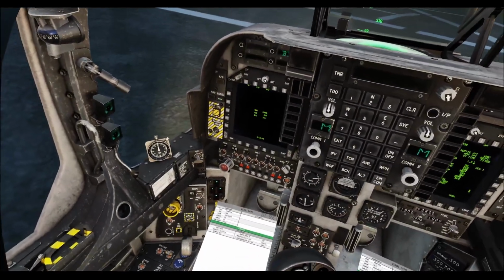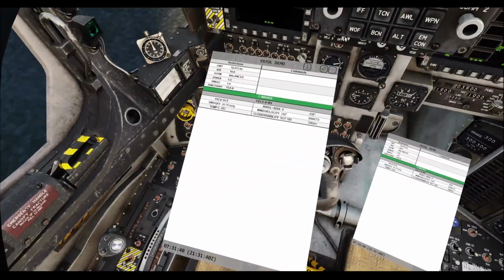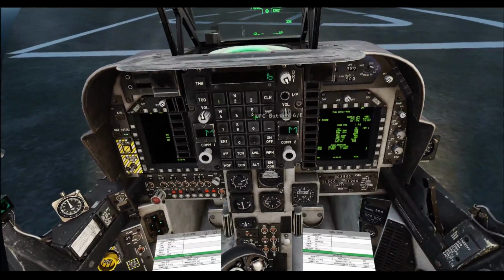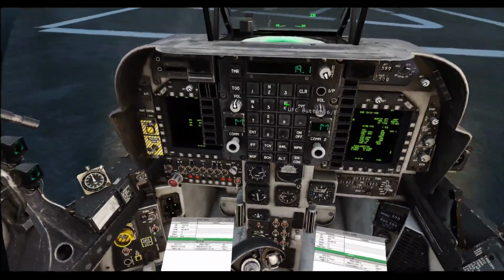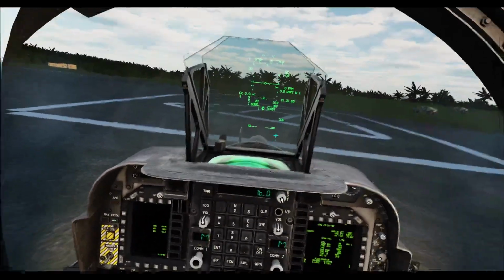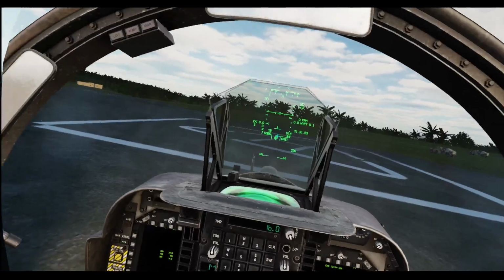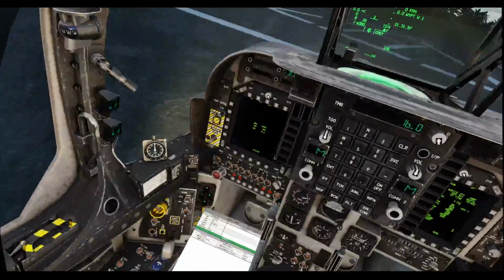So coming over here into the VRES page, we're going to overwrite the basic aircraft weight with the operational weight, which is 16,475 pounds. And the BDI to 16, that's your basic drag index. Obviously, that's more important for fuel endurance calculations by the crew section of the VRES computer. Not important here, but it's good to have that habit.